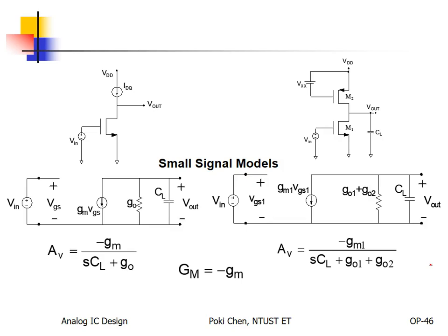But for me, again, what I told you. First of all, you convert Vin into Iout. Right? So what is Iout? gm Vin. Right? And then, what is the Vout? Iout by Rout. But if this one is perfect, then you have only ro here.